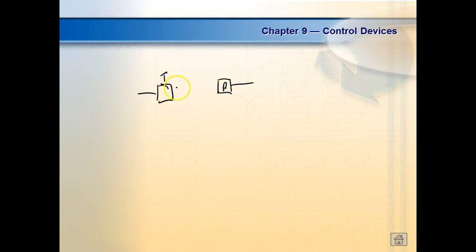And then what we do is we shoot a light beam across. And then if the object comes through here, so these guys would be true all the time, right? That makes sense? Their outputs would be true. And then when the object comes through and breaks the beam, then it would know the object's at a certain place. That's what we call this guy. We call it through the beam.